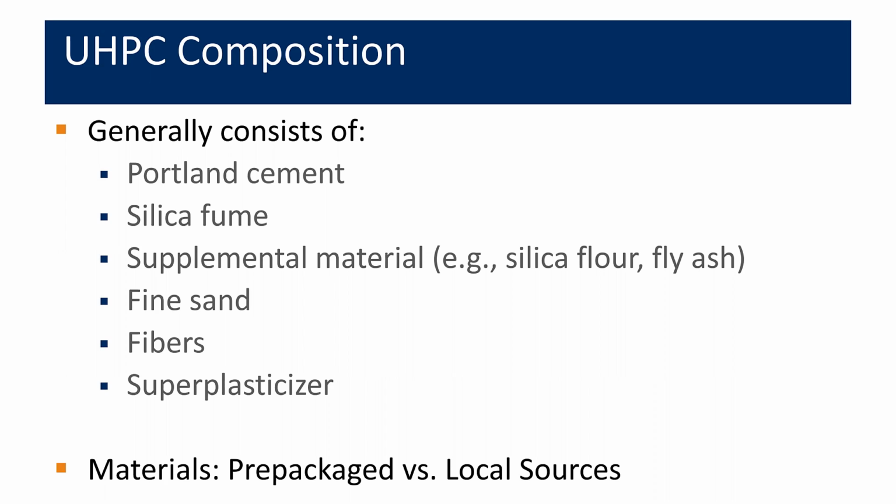So there are different fibers that may be used. And also certain polymeric fibers can provide fire resistance as well. And finally, the UHPC is going to consist of superplasticizer. These are typically polycarboxylate materials. So these are very efficient superplasticizers for materials that contain high volumes of powder material. And you'll use them at several times the dosage that you might actually see in conventional concrete.